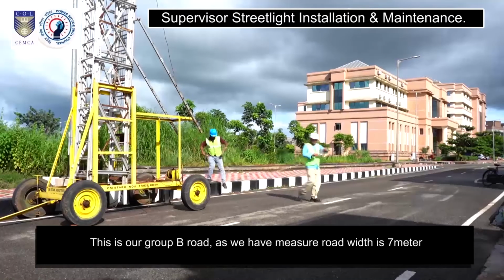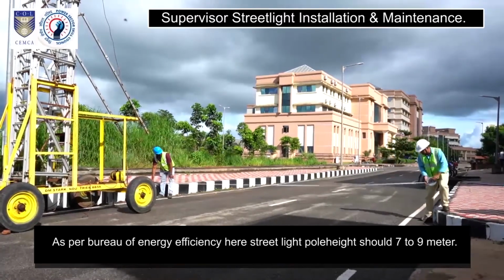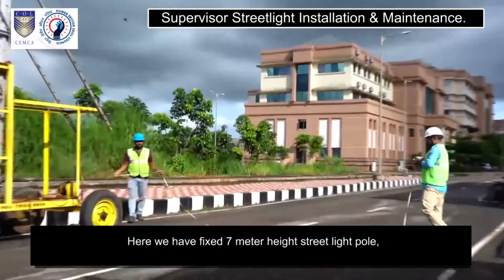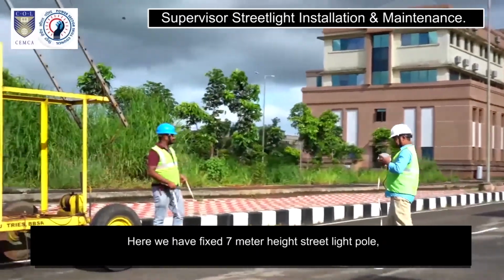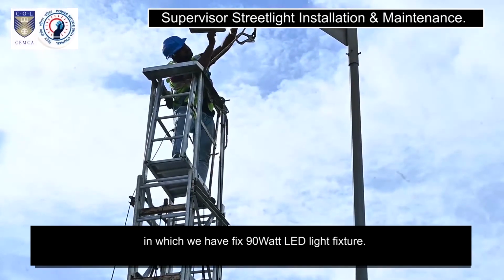This is a Group B road, as we have measured road width is 7 meter. As per Bureau of Energy Efficiency, here streetlight pole height should be 7 to 9 meter. Here we have fixed a 7 meter height street light pole in which we have fixed a 90 watt LED light fixture.